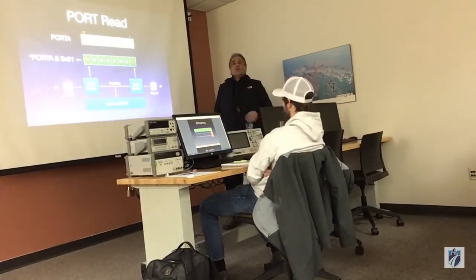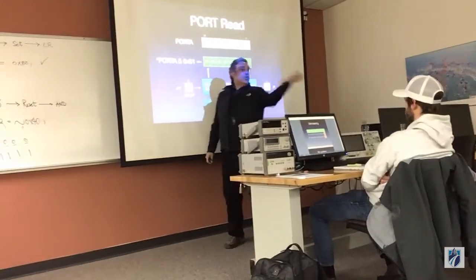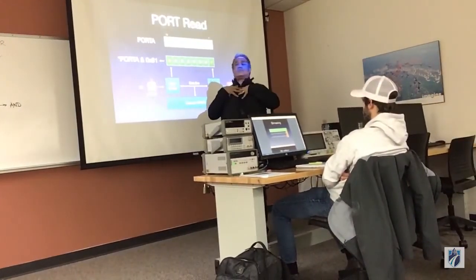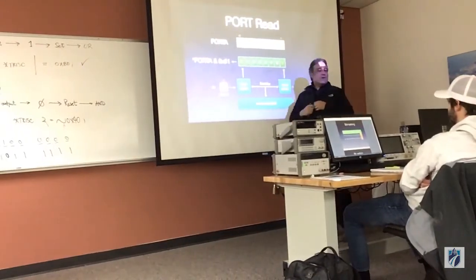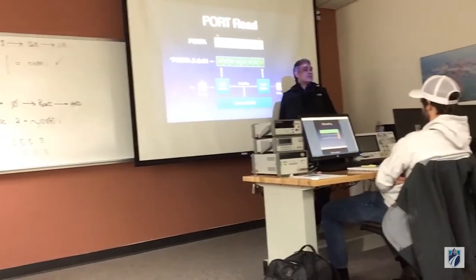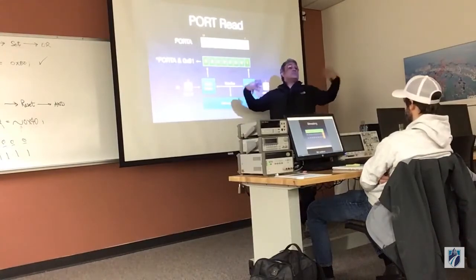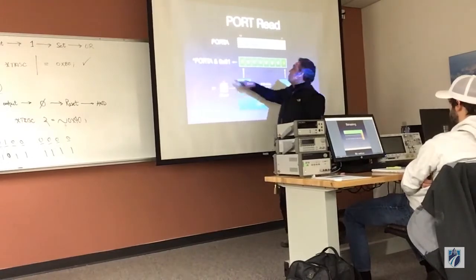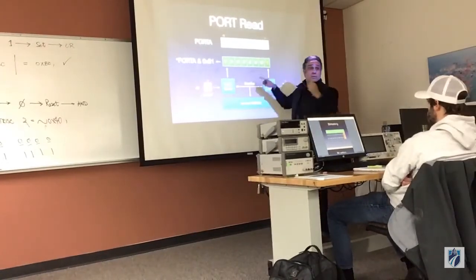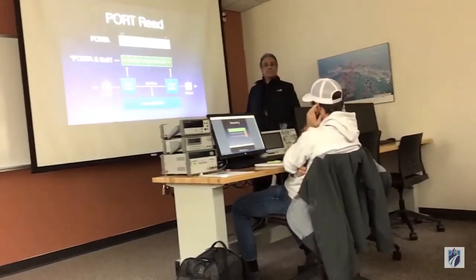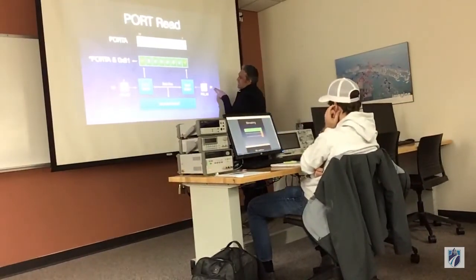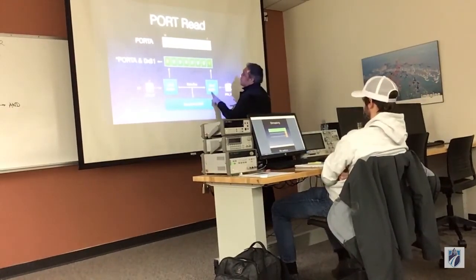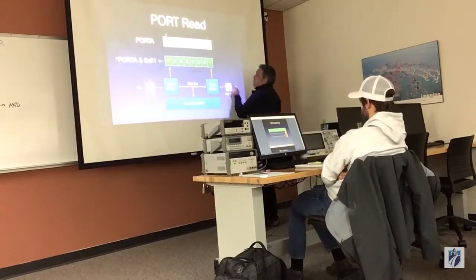See that? So this software is your choice to do at a specific moment in time. You can say, I want to see what's happening at A7 and at A0. Assuming that it was set up right, what is the instruction that allows me to see it? The answer is that one. Right? I can take this instruction and monitor what's happening there and there. The circuit will take care of the rest. If I put 5 volts on pin A2, on pin 0, meaning pin 2, the 5 volts will go through the buffer into port A, and the 5 volts will become a logical 1.